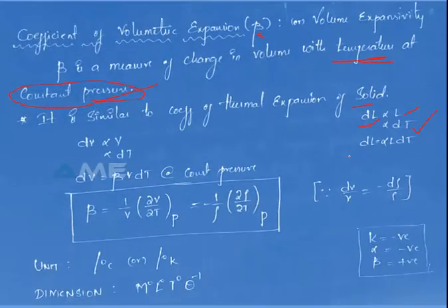In the same way, we are also taking the change in volume with respect to the volume. Change in volume is directly proportional to change in temperature. To equalize that, you take the coefficient of volume expansibility, or volumetric expansion, at constant pressure. If you simplify this, you get beta equals 1 divided by V, times change in V with respect to temperature at constant pressure.